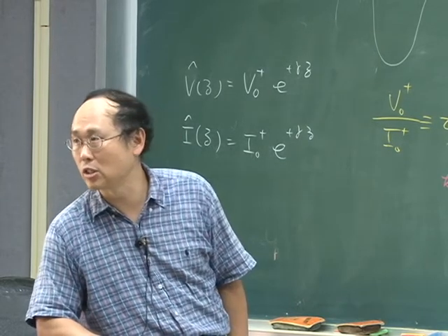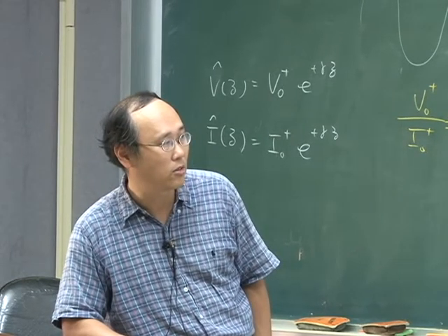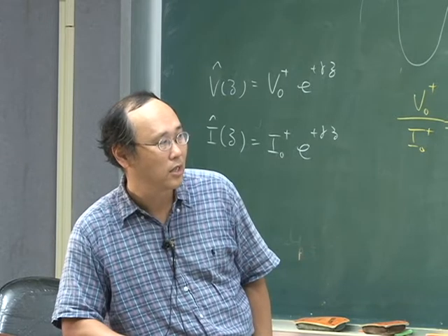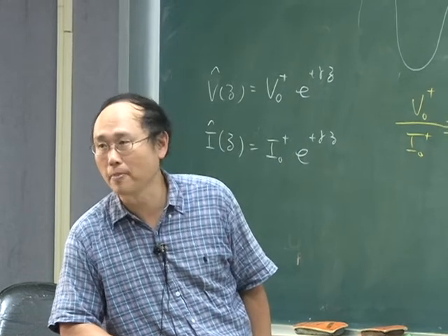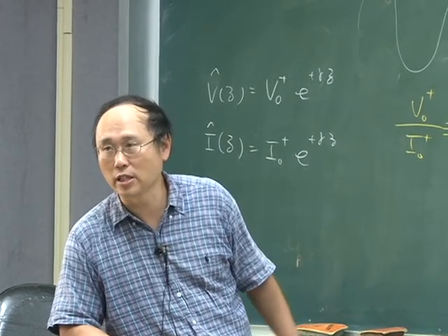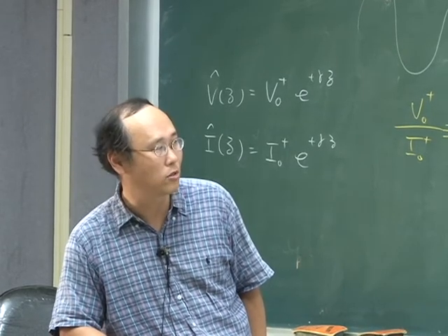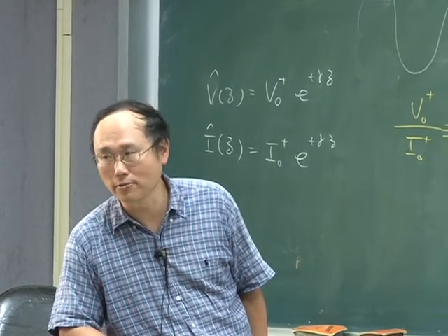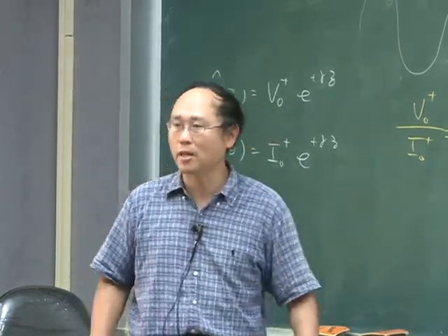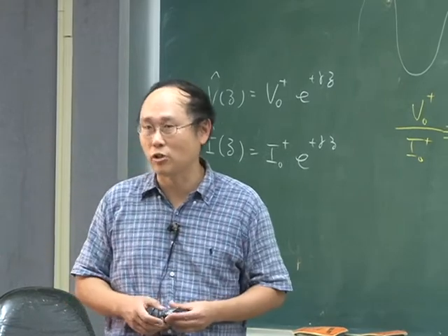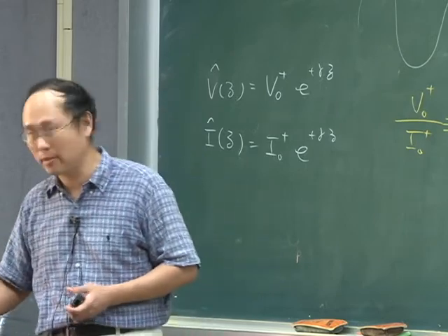You can express this gamma in polar form, giving the magnitude multiplied by a complex exponential. Since it is a complex number, it has a phase, and the reflection coefficient can be negative or positive. So this is the reflection coefficient telling you how much of your signal is reflected back from the transmission line. And of course, you want to minimize this ratio.